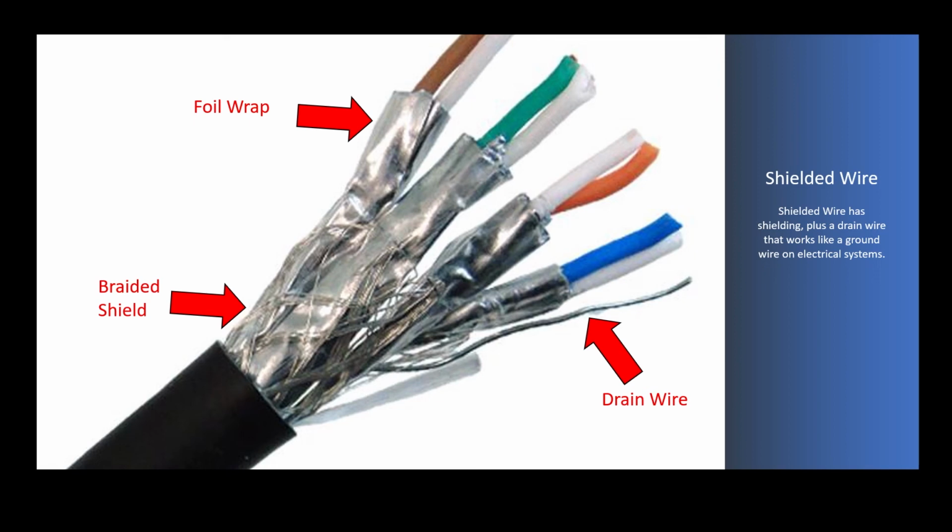So you need to get that to ground somehow, and it needs to be on both ends of the cabling all throughout the system from plug to plug, essentially. And both devices have to be engineered correctly with metal plates to take those metal things from the cabling itself. So everything needs to work, otherwise it ends up possibly being worse than not having the shielding at all.